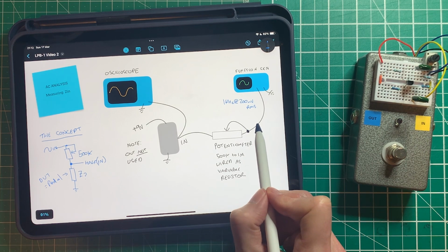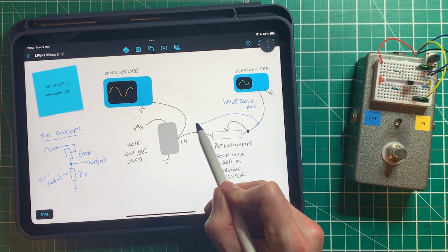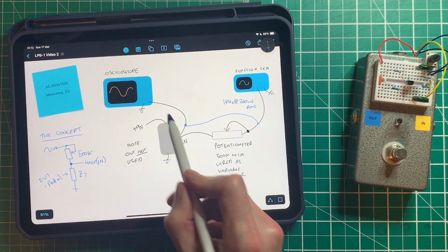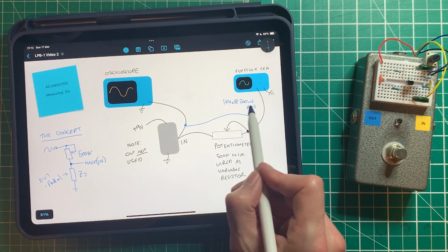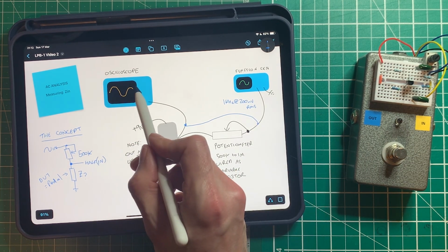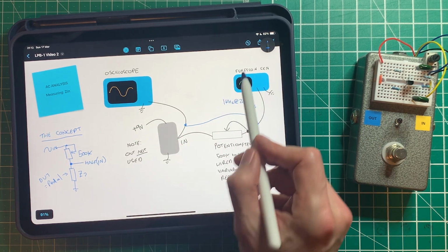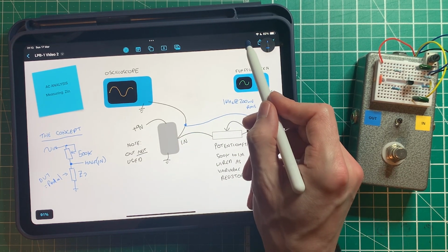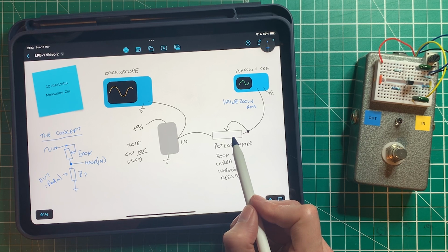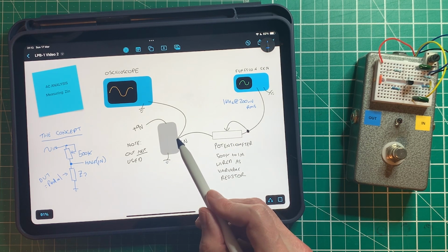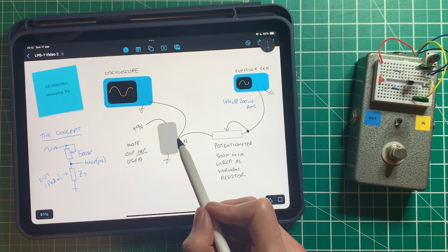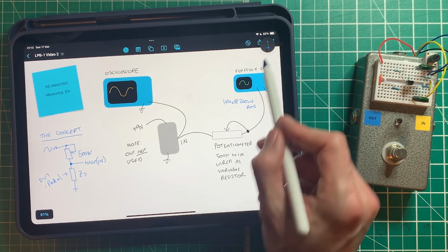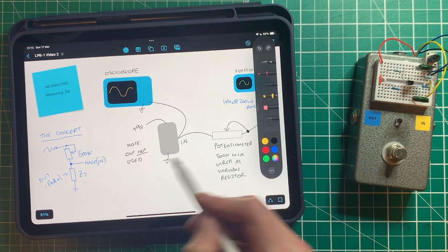First of all, we'll send it straight into our oscilloscope and we'll make sure that it's 200 millivolts and we're seeing that on the RMS. Then we'll remove this and we'll send it through a potentiometer first and then into our input, and we'll also hook up the oscilloscope to the exact same input. We are not using the output. I think I might make that very clear.